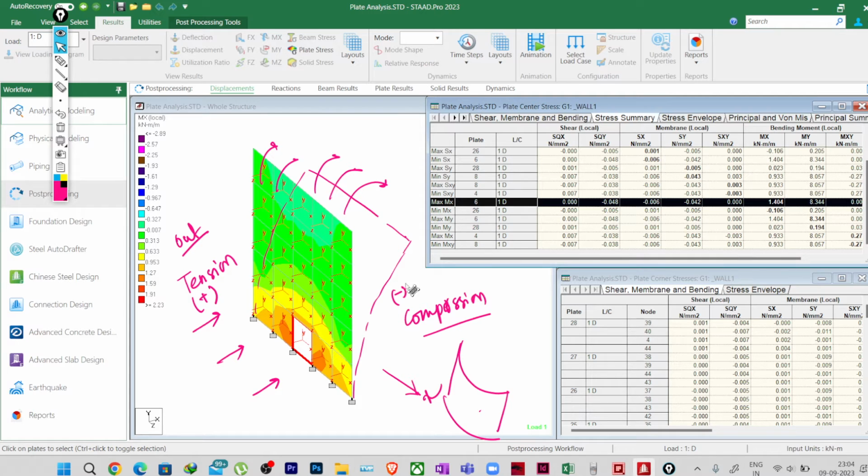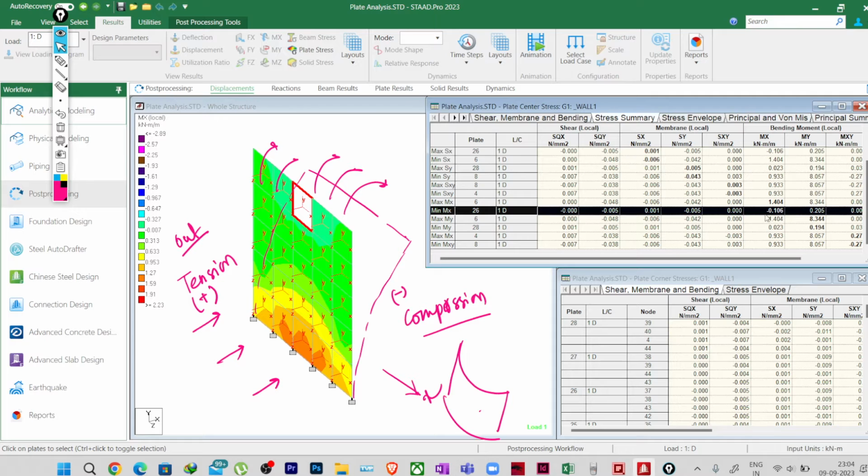And if you see here where we will be getting the sagging, obviously at the top area, because the top is going this direction. So if you see here, if I click on this negative moment, which is the compression face, right? That means the inner face. So that is in the negative value. And we expect that the moment along y, the vertical direction moment, will be higher, and in the bottom location it will be under higher tension in the outer face.